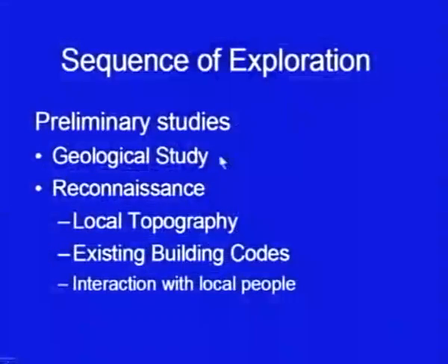When you plan an exploration, the preliminary studies have to be carried out first. It includes, as I told you, the geological study. Then you can have a reconnaissance of the site. You have to go to the site, then look at the local topography, look at the existing building codes. Also, sometimes it is very helpful if you interact with the local people and find out what kind of the strata, what kind of the problems they are encountering as far as the soil engineering is concerned.